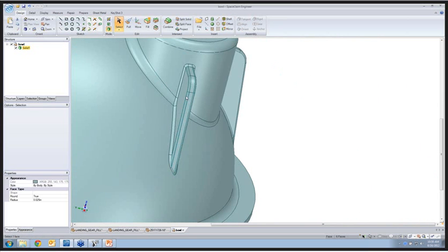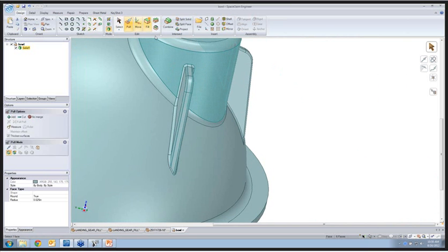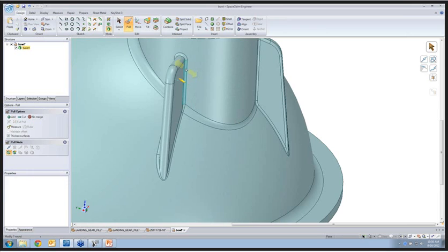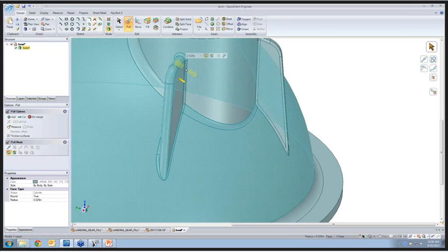But even with something that was already created in another CAD system, I have the ability to go in and edit the radius of those rounds. The ones on the outside, I'll change to 50 thousandths. This engineer spec'd these out to be 25 thousandths of a radius, but I may only be able to get a 1/4 inch ball mill through there, so that would leave about 1/8 of an inch radius.